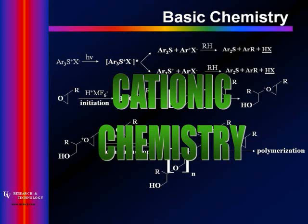Cationically, UV-cured coatings have become an important part of the overall UV cure market. However, the cationic market represents only about 3% of the overall radiation curing industry, with 70% being found in beverage can manufacturing. Cationic chemistry is less understood than the free radical-based systems, and formulating skills are rather limited. In addition, the availability of raw materials is confined, and are in the majority, based on epoxy resins.